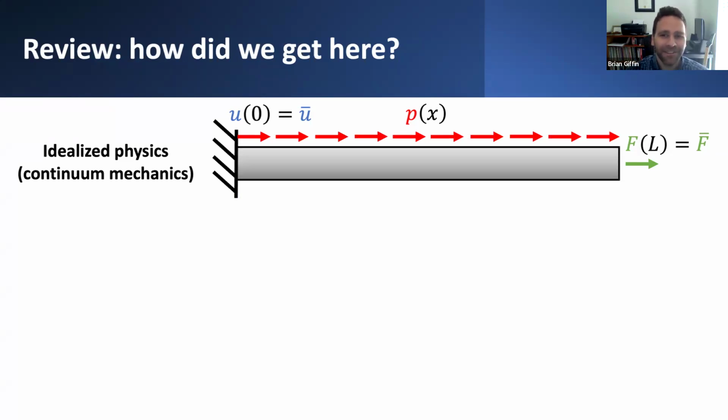We idealized the physics of these problems, nominally treating them as homogenized or continuous media, assuming that we're restricting attention to physical behaviors. We imposed some other constraints like the assumptions of linear elastic material behavior and also small deformations. So there's a lot of simplifications that went into idealizing the physics and turning it into an equivalent mathematical problem.